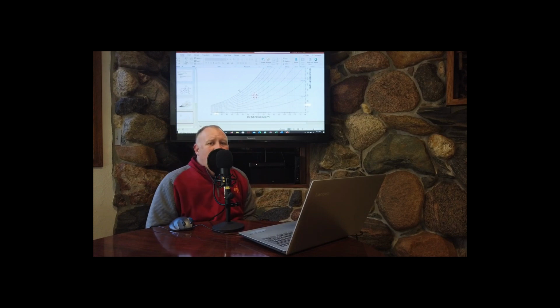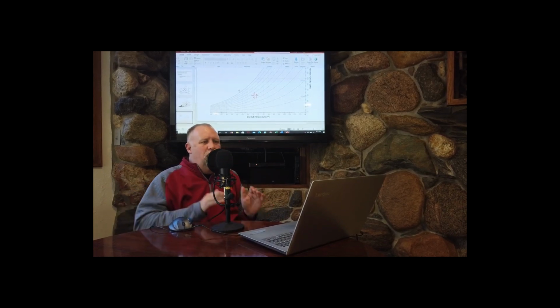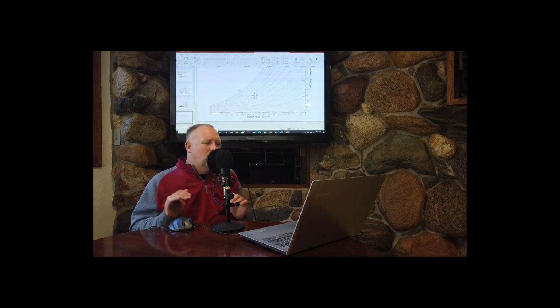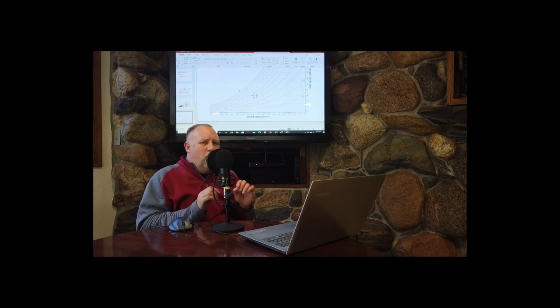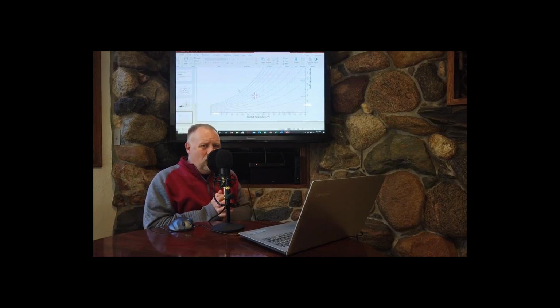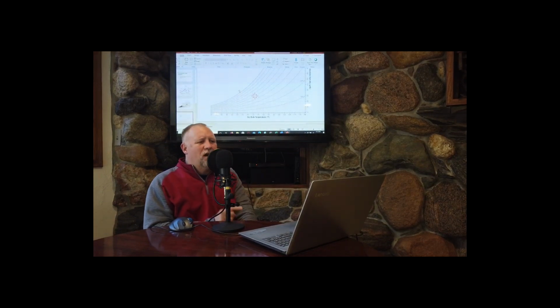Try it. It's important that you get the enthalpy correct, because when you're doing problems, looking at sensible load, latent load, and total load, and you also use the 4.5 times the CFM times the difference in enthalpy to get your total coil load, the easiest thing to read wrong on this chart is enthalpy.